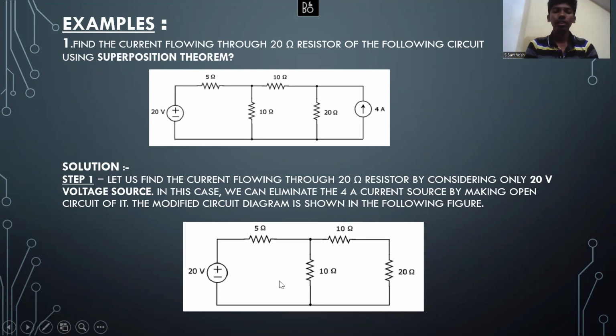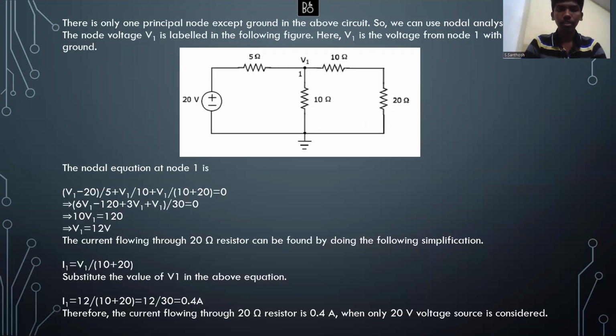Now while solving this circuit, you can use different methods like loop analysis, node analysis, KVL, KCL, etc. Over here, let's try to solve this question using node analysis. In node analysis, you just consider a separate node. Let's say we'll consider this node over here and take it as V1 and solve to find the voltage V1. So we consider this as V1, and this node we consider as the earth node or base node.